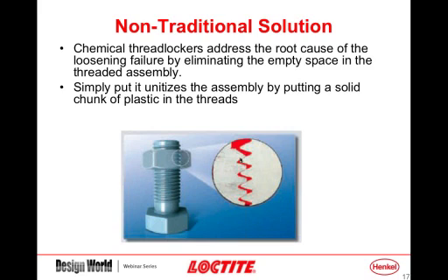And in this case, you actually have two counteracting forces. One is it prevents the relative movement of the nut and bolt by preventing the relative motion of the threads side to side when you have all that impact going on. It actually prevents the side sliding and therefore the loosening. And the second effect that you get is this is an adhesive material.